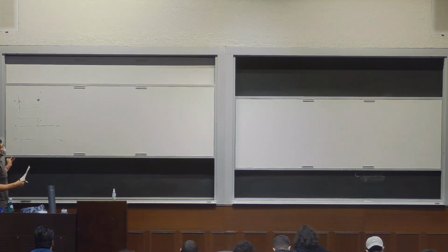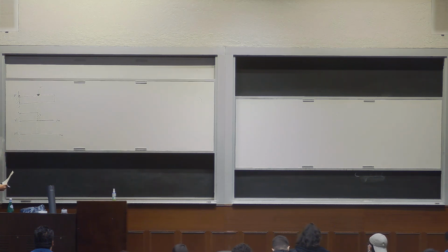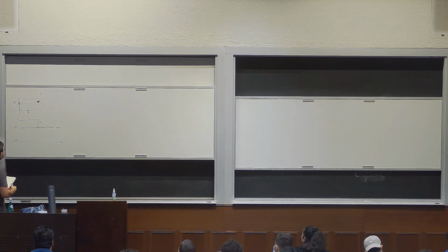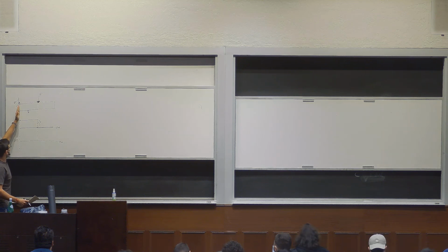Now, the moment is related to the shear force, namely the shear force is the derivative of M. So let's think about the moment that this P could be applying. If this distance here is L, and this beam is 2L, then the bending moment acting at x equals 0 is the force times the moment arm, so it's PL.